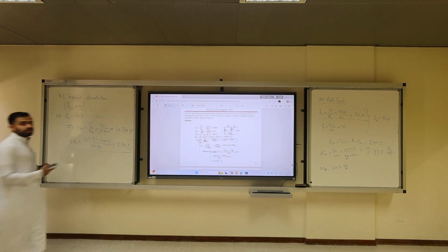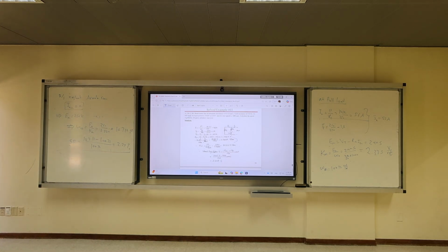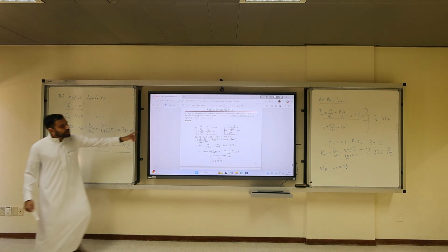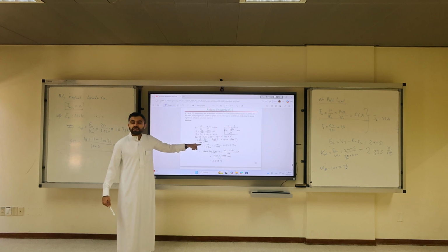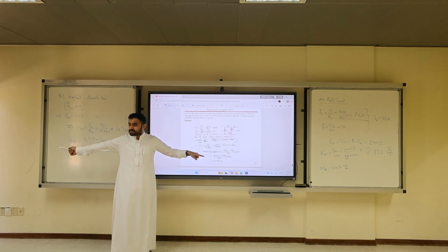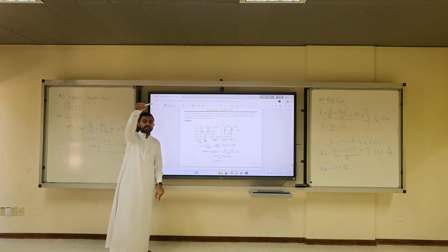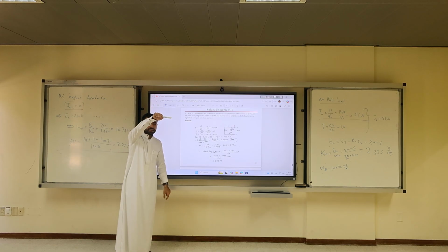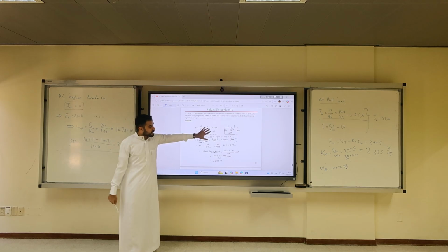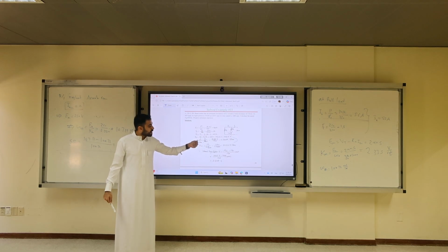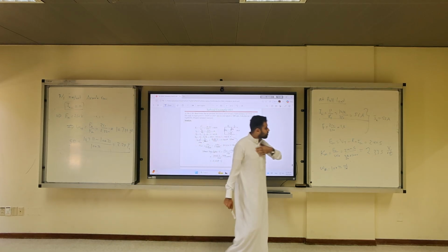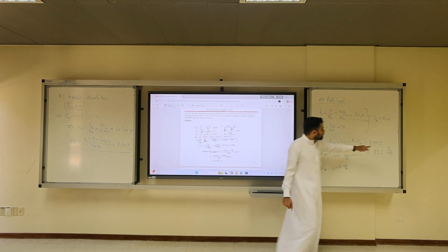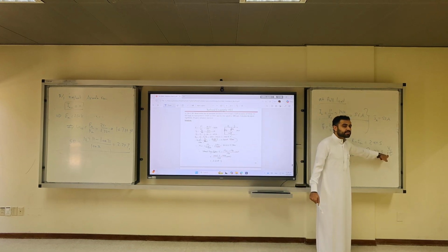So this is if we're going to solve it using our formulas. In the slide, how did he solve it? He got the constant as a function of V over RPM directly, without changing to omega. Get it? In the slide, he got the constant K times the flux as V over RPM. The way I did it, our own method, is get the constant as V over radians per second.